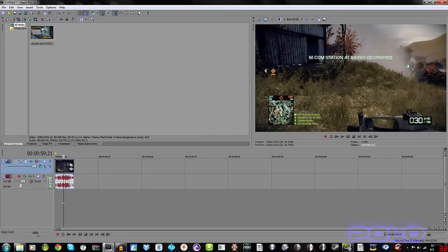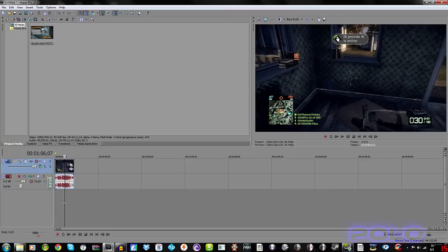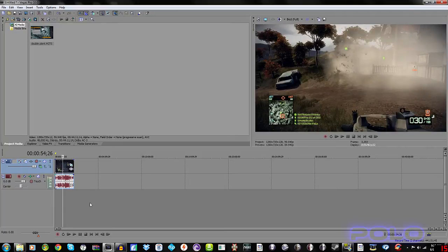Another thing, and you might not understand this right off the bat, but the way the PVR captures is with an analog signal. Those color-coded cables, that's an analog signal. HDMI is a digital signal, and there are devices that capture with HDMI, which is a nice, sharp, clean digital signal. But analog is not quite as sharp. Everything is still kind of feathered a little bit. It's not quite what it could be.